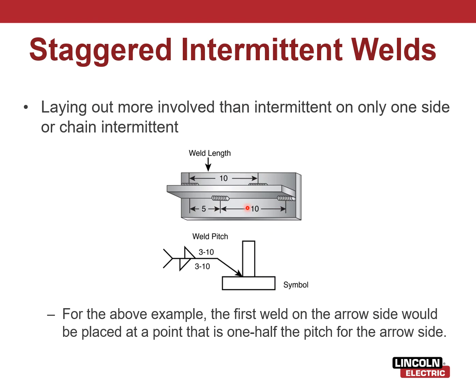Usually when you're doing stuff like this, you'll lay it out and then tack the beginning and end of the weld. And so you've got all your 2-inch or whatever, right? These are 3-inch, so you would have a tack 3 inches apart wherever those welds are going to lay. That way you could just drop your hood and burn all those segments between the tack welds in.